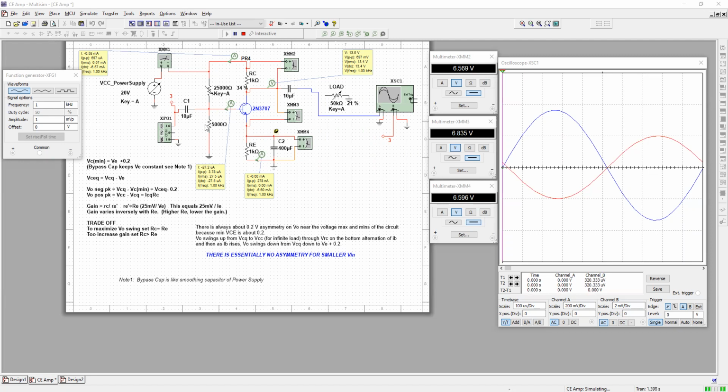The load would be in parallel with the bleeder resistor, which is this 5,000 ohms here, and it would create an equivalent resistance that's less. That changes the ratio of the voltage divider. So the larger your load, the less effect you felt when you added it.